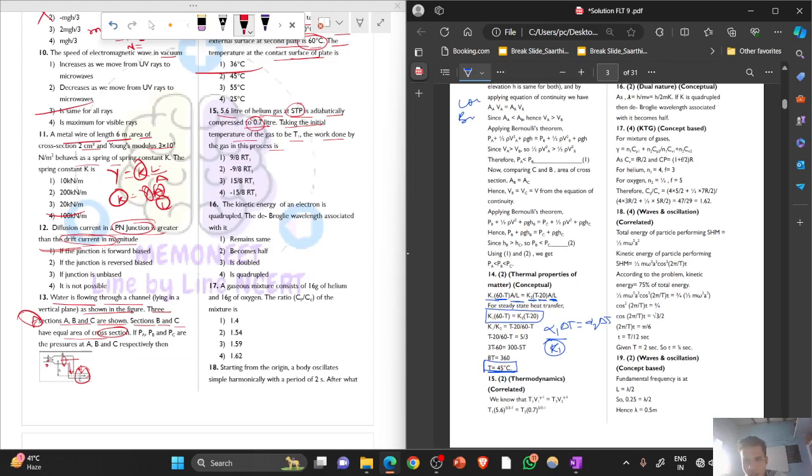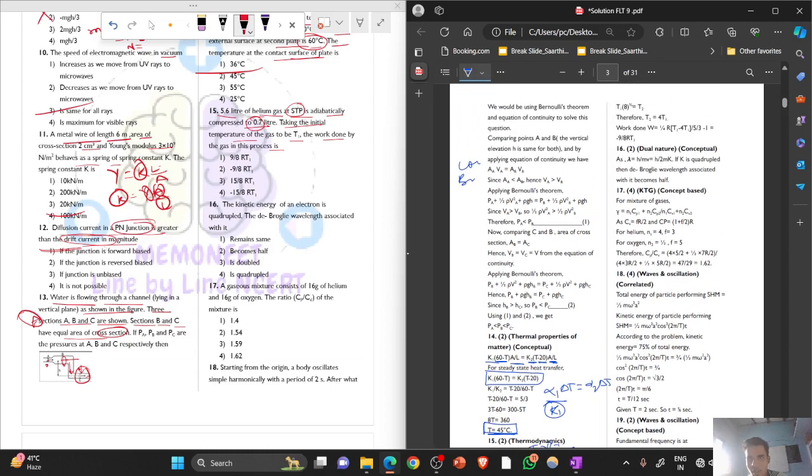Your adiabatic equation in terms of temperature and volume is TV raised to gamma minus 1 is constant. Putting the values of T1 and T2, the initial will be T1. You don't know the final temperature, but you know the initial volume is V, and it will be compressed to 0.7 liter, so the final will be 0.7 times V. From here you get the value of T2.